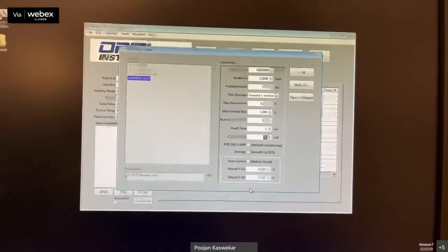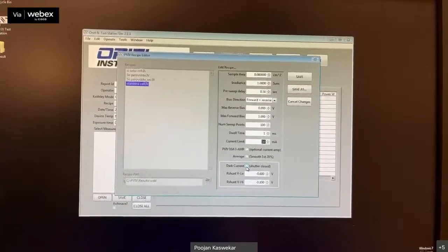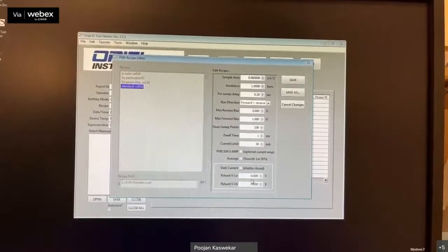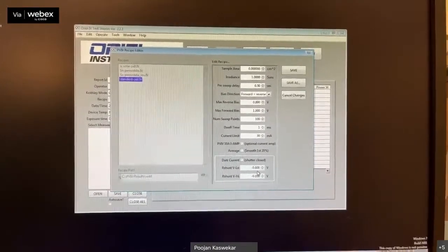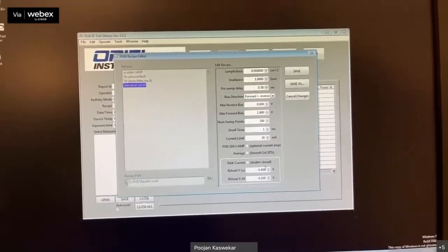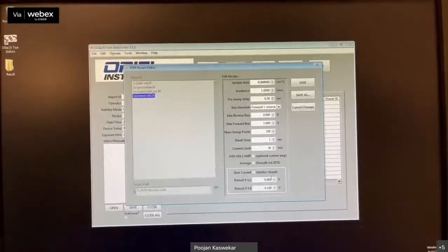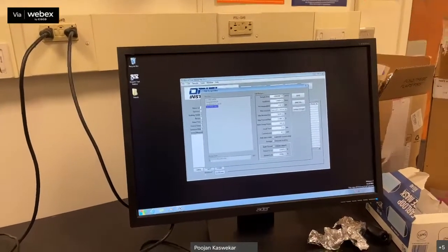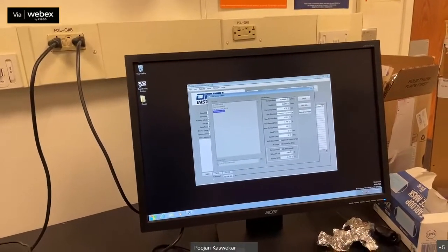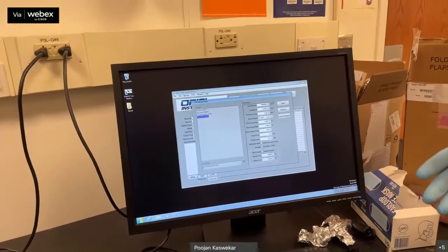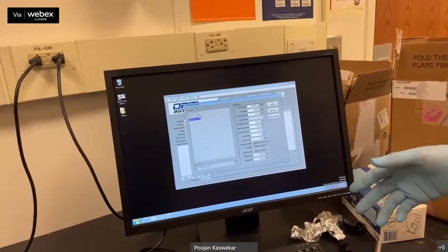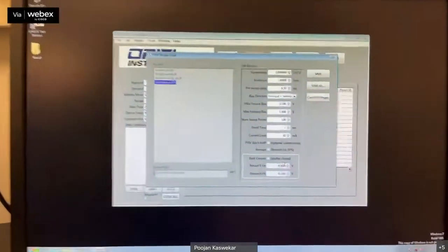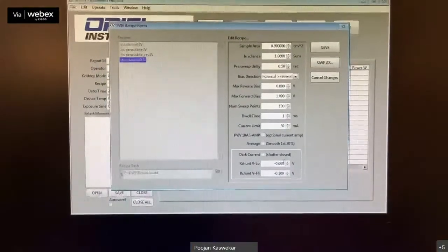And if you want to measure the dark current, you put dark current, shutter closed, and R shunt, voltage low and voltage high. It will typically be from minus 0.1 to plus 0.5 V. You'll see a dark current curve like a V-shaped curve going from negative to positive. After that you'll see the shunt resistance, then the series resistance. So when you want to see why you are losing VOC and the other characteristics, you typically do dark current characterization. And from the illumination characterization, you get your JSC.